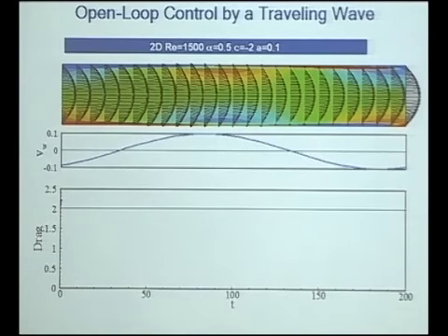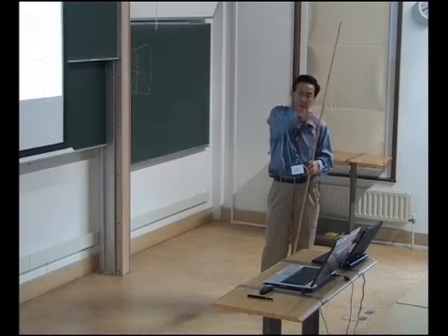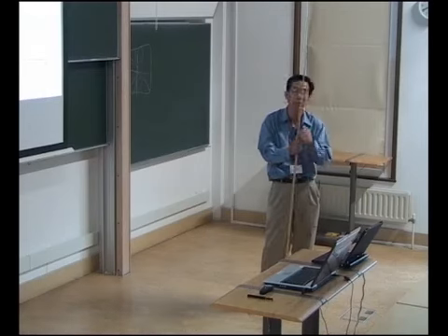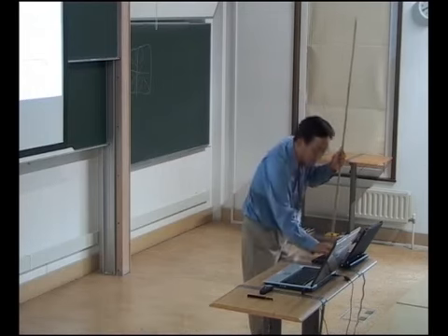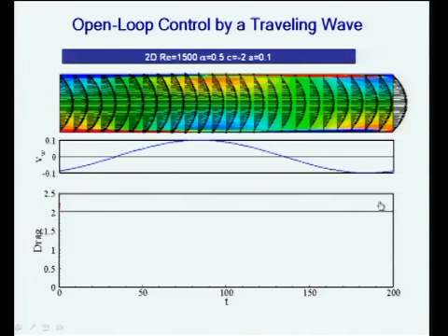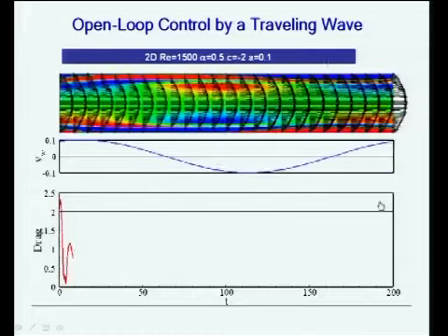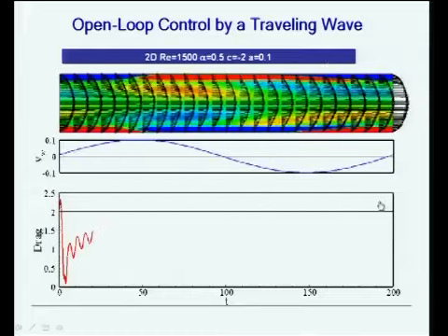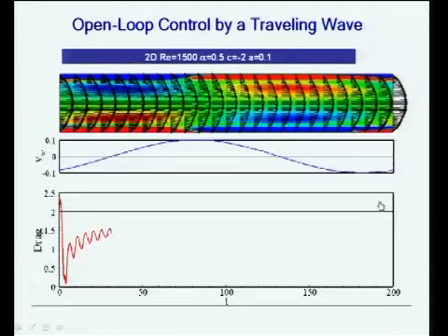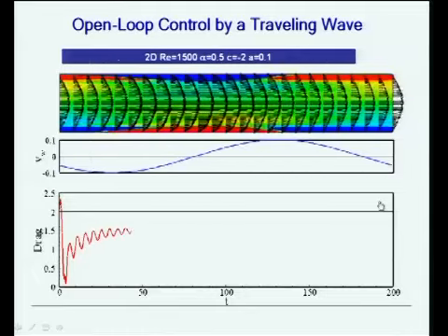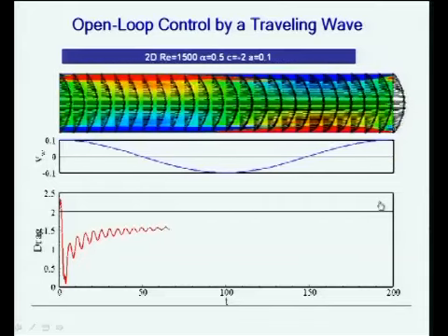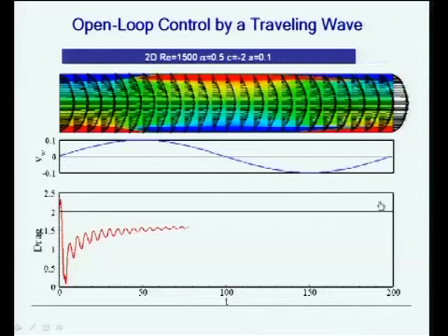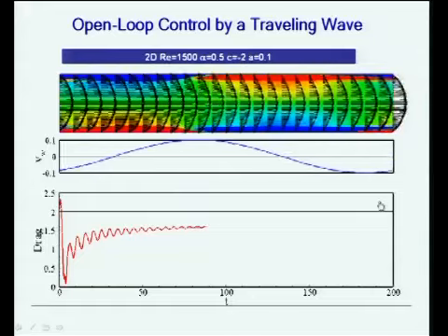Now, we actually found this work serendipitously, because we were looking for what the control people call periodic control. Instead of basing it on some steady state, we want to drive our system in a periodic state and then apply the control based on that. During that process, we applied blowing and suction at the wall, at various different wavelengths and various different wave speeds.